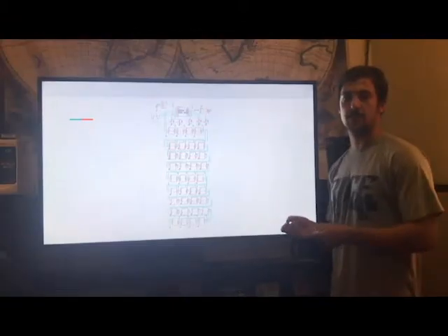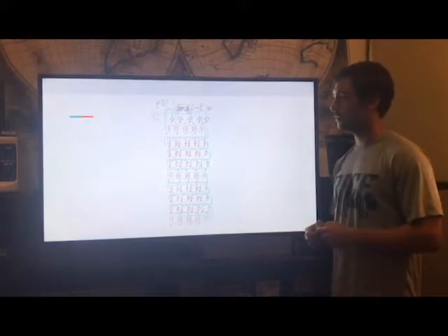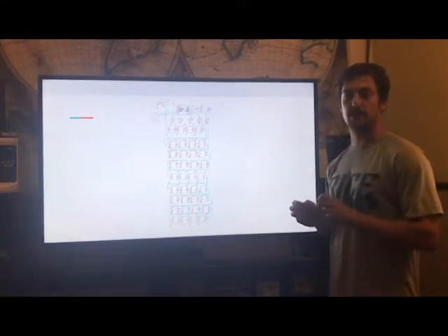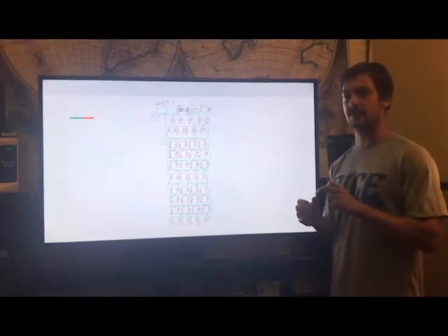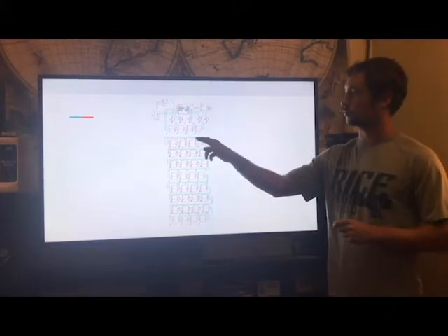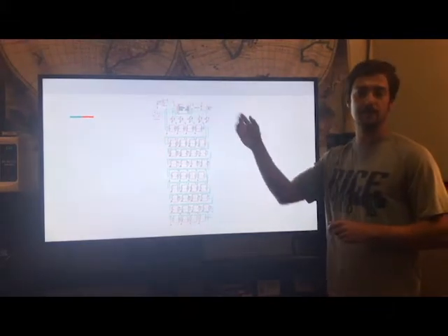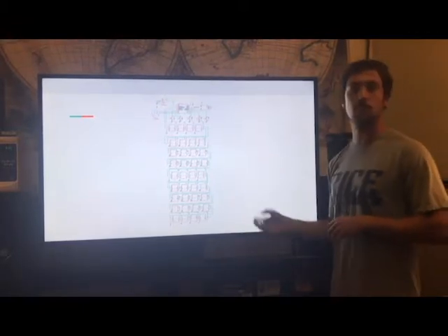Seen here is the schematic we used for each individual face of our project. And since we were thinking about it thoughtfully, we were able to replicate the same exact face for each of the 6 faces of the cube. Seen here is our array of LEDs, which is what the MSP430 is going to see: not a grid, but essentially a single row of LEDs.